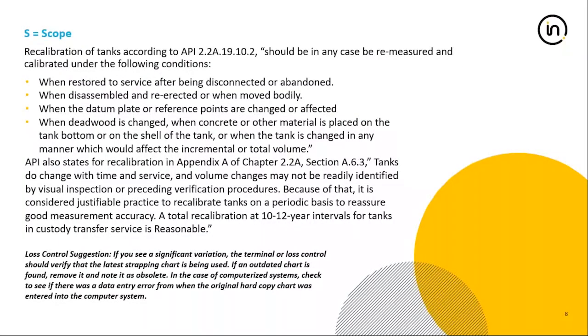And now we're going to go over why and when you have to calibrate or recalibrate your tank. The API recommends that you recalibrate your tank when one of the following conditions happens. The first one is when you restore service to a tank that was previously disconnected or abandoned. The reason is that even though tanks seem very solid structures, they shift and warp over time.